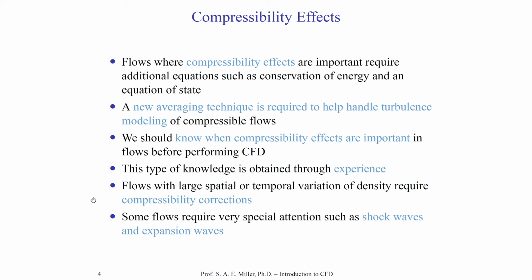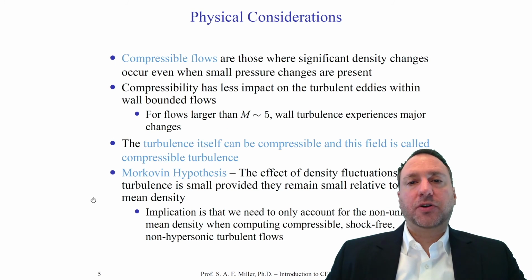And so we use shock capturing techniques to reduce the number of grid points and also accurately resolve the shocks. This is also a compressibility issue which we must account for. Compressible flows are those where the density changes, and accordingly small pressure changes are present. Now, mathematically, we would define a compressible flow as one where the fluid parcel does change volume as it moves through the fluid domain. That is, the volume of each fluid parcel changes with time.